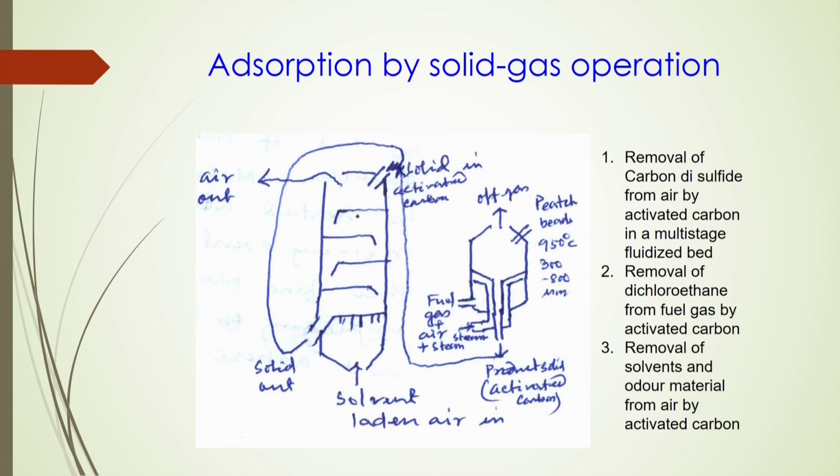Now, another important one is adsorption by solid gas operation here. If you want to remove carbon disulfide from air by activated carbon in a multi-stage fluidized bed, what to do? You have to supply this carbon disulfide and air mixture to a bed of solid particles of activated carbon, and then at a certain flow rate and at a certain temperature you can remove that carbon disulfide.